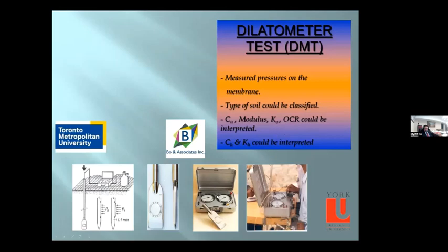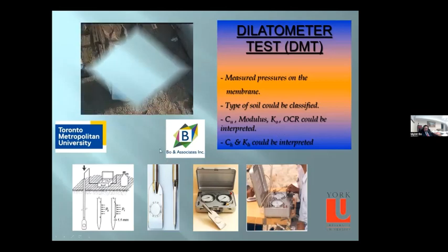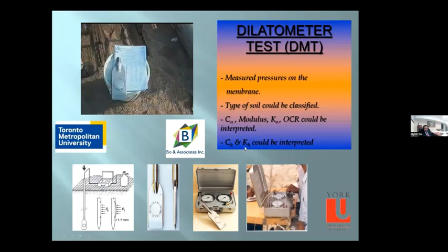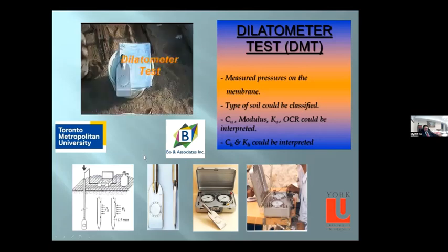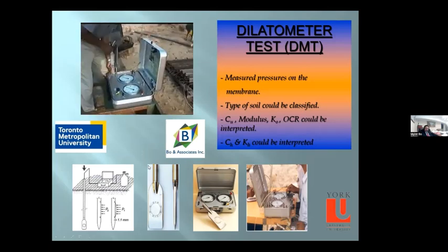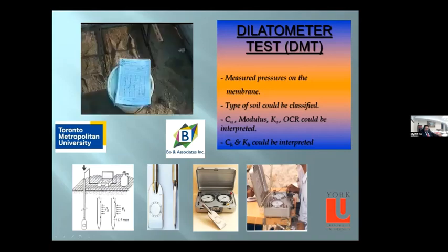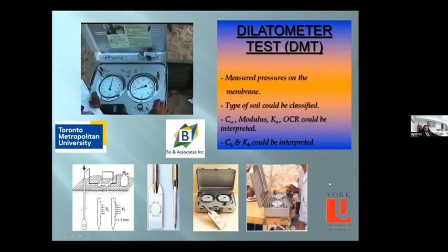Also, they can carry out the dissipation test, and from there they can determine the coefficient of consolidation. This is a dilatometer test being carried out.